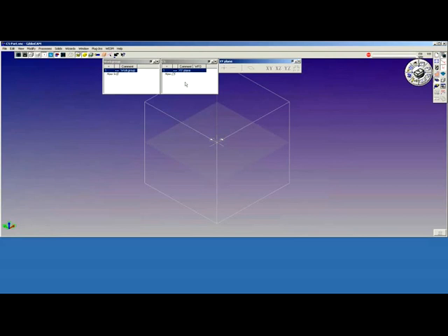When you build a new coordinate system, it's done by clicking on the new CS tile, and the new coordinate system is a duplicate of the active or existing coordinate system. So when I click on new CS, I'm not going to see any obvious changes on the screen, simply because I'm duplicating what's already there.